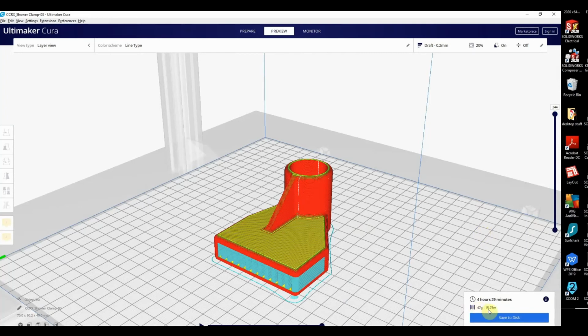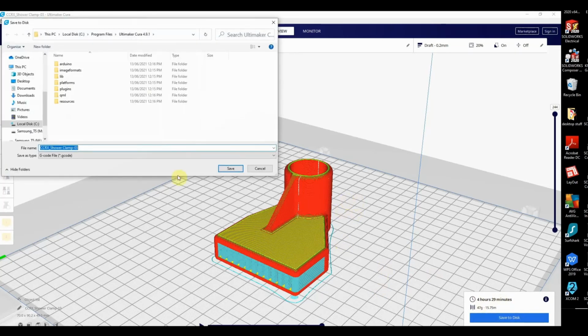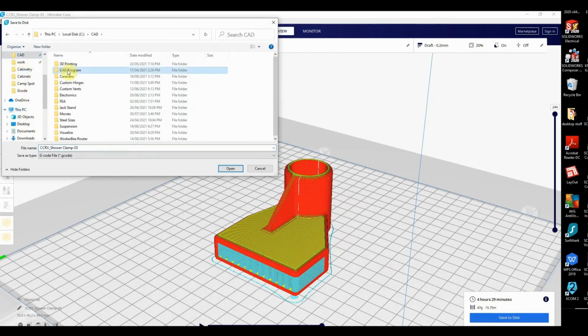So here it tells us the amount that it plans to use. It plans to use 15.57, which gives us a cost for the material and a time for the machine. It says it's going to be 4 hours there. So we roughly know that it's 7 cents per hour. There's 28 cents of running this machine to do that.